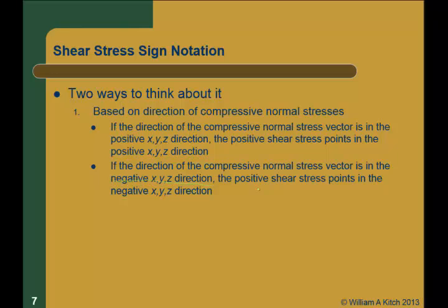If it's a positive plane, positive shear stresses are in a positive direction. If it's a negative plane, positive shear stresses are in a negative direction. So this is one of those cases where two wrongs do make a right. You know what your mom told you.